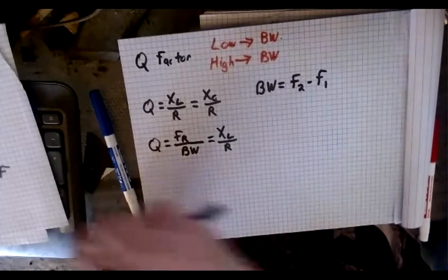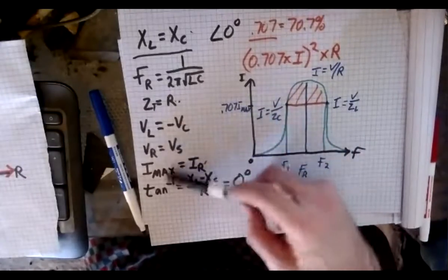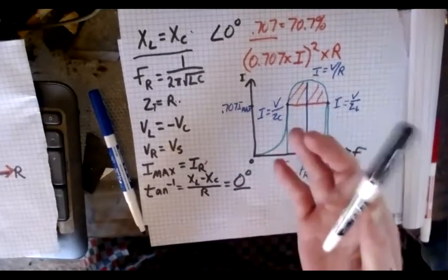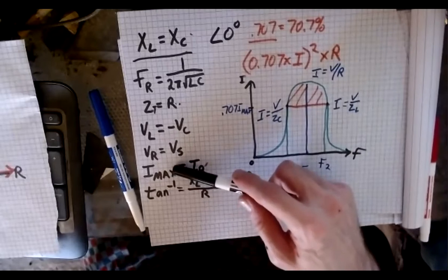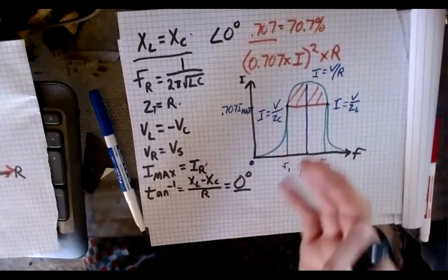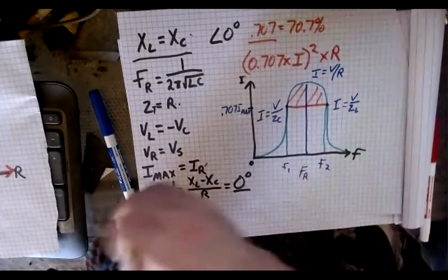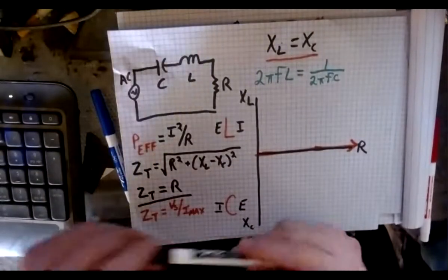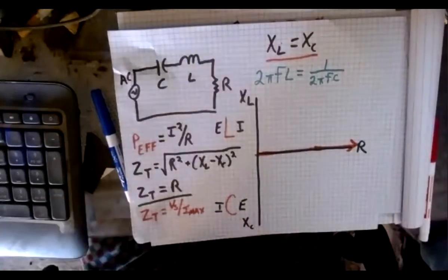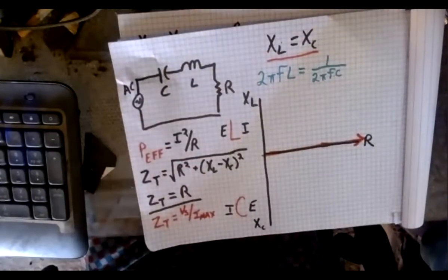Because this end, right, we were able to go through and quickly do, and everything was based around voltage change ups and getting what my current was. Now we know in a parallel network that this is going to be slightly different because of the branches. So our way of analysis varies a bit. We'll still be going through pretty much the same method, but tomorrow when we go before the lab, we're going to do a run through much like this. So we know what our rules are for a parallel resonance circuit versus the series resonance circuit.